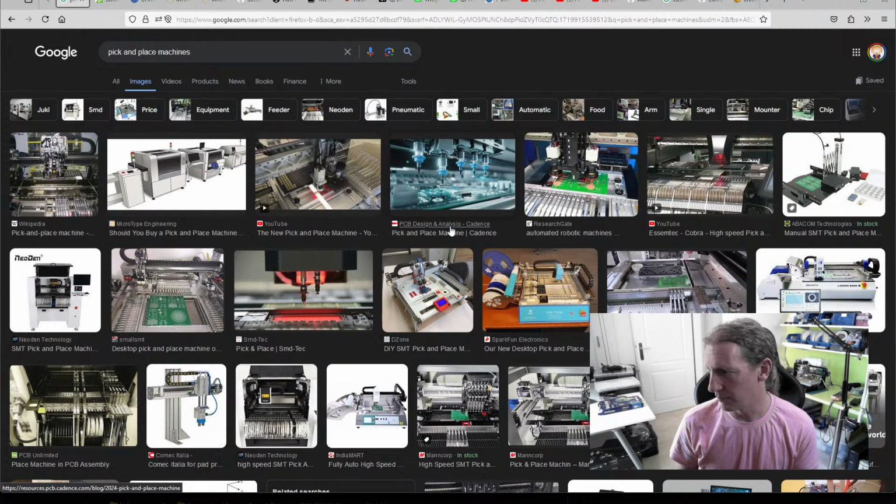And in order to operate a camera switcher, you need various GPIO outputs and so on. So normally one 3D printer control board can't handle a pick and place machine. You have to get the fancy ones, and even they don't have support for the vacuum sense lines, for the vacuum pressure. So one solution to this is to buy 2 cheap 3D printer boards and then have another board which has the vacuum sense lines, or to buy a dedicated board which just basically has everything.